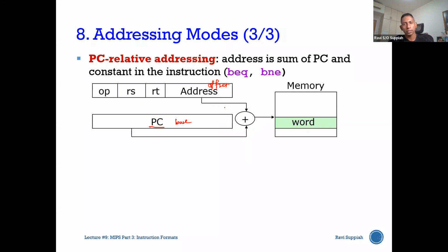But in this situation, the final decision is to change my PC, my program counter, whether I'm going to PC plus 4 or to a new address. So you can see that it is the same I-type instruction, the same sort of format, yet because the instruction is different, we are doing many different things.